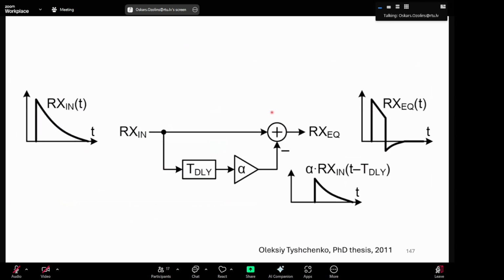So what's happening there is why it's called a feed-forward equalizer, because you take a sample, and you need to change the shape of this decay here. You need to decrease it, so you need to make sure that your impulse response stops here. So then you apply a compensating signal just to compensate out this part.